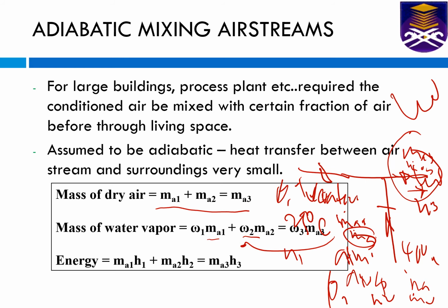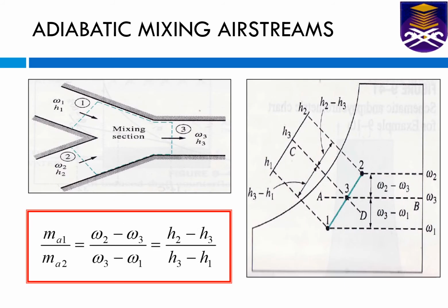So for example, from 40 degrees Celsius and 25, let's say it comes up here at 30 degrees Celsius. Going from 30 degrees Celsius down to 25 or to 20 degrees Celsius needs much lower energy consumption to reduce the temperature for the air conditioning process. So this is airstream 1, with the assumption that the process is adiabatic. Okay, so how do we come up with this?